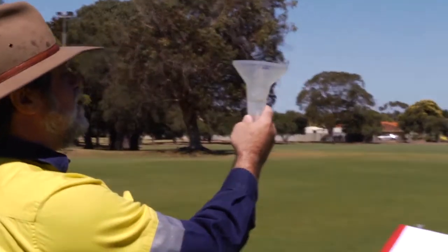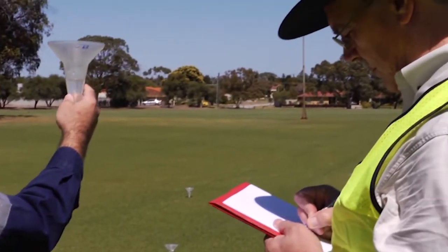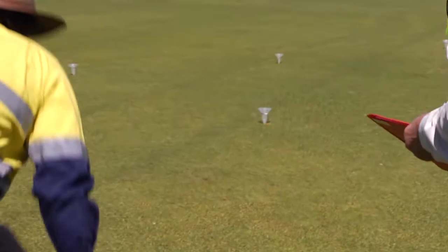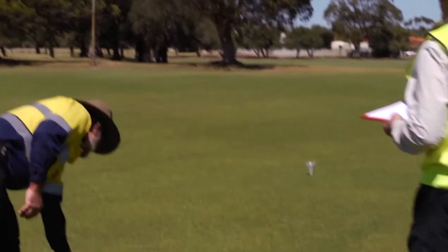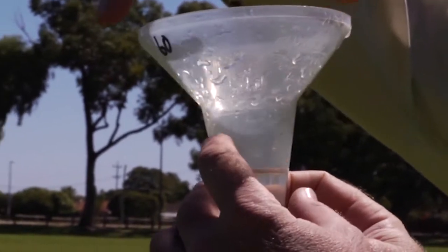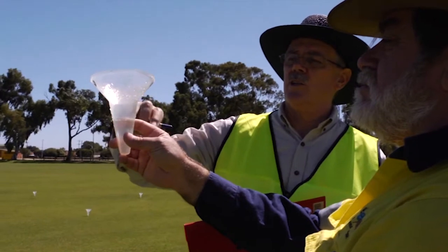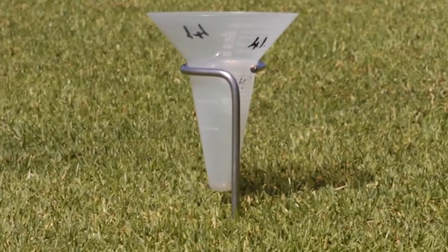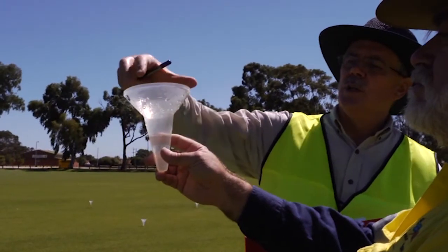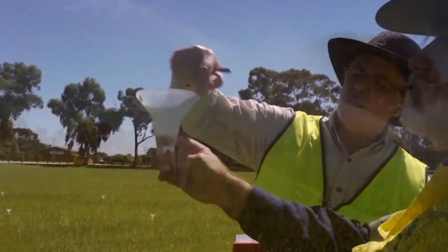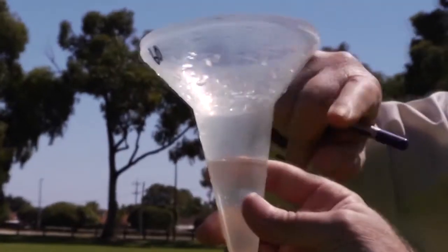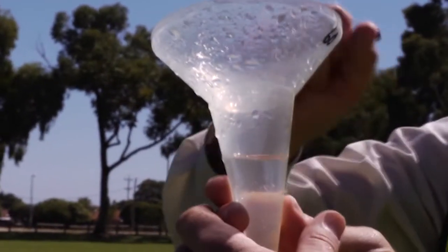Following completion of the test runtime and after the pump turns off, readings are taken and recorded for the amount of water collected in each cup. These cups are specially designed for the purpose of catch cups in this application. They're calibrated and they've got a tapered holding receptacle at the bottom. So you get a large catch area, about 100 mil, and that's collected in this tapered section. One side is calibrated in millilitres and the other is in millimetres.